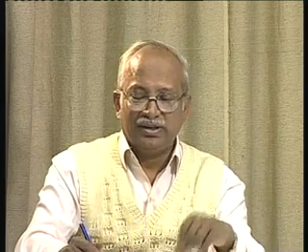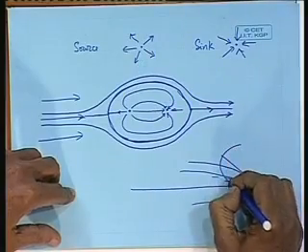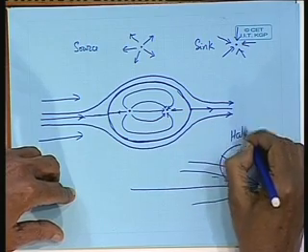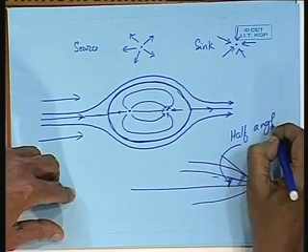I know that it will be there, but it will reduce as the point dips more and more below the free surface. So, maximum impact is of that slope near the waterline. So, if I can reduce the slope on the waterline, then I can control my wave making resistance, and this angle is called half angle of entrance.